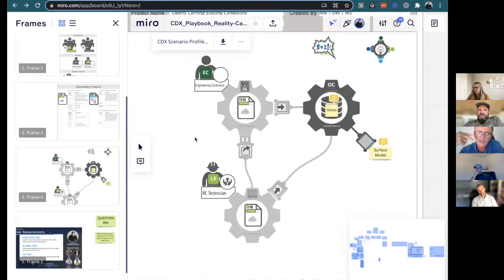Issue number two: how can I make this data easier to view and interpret? The difficulty of using point cloud is that you see through the dots, and if you try to make a simple measurement, even in Revit, you may pick the wrong points, because you are not looking at surfaces, you are looking at a set of dots in space.